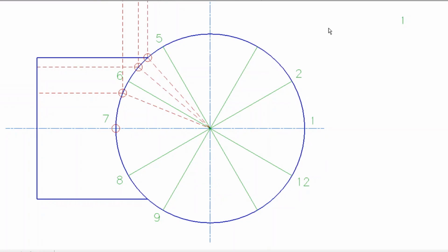With the grade 11 drawing, you're going to be using 4, 5, 6, and 7 directly as your points of penetration, but because this cylinder here is smaller than the main, your penetration points will not line up with 4, 5, 6, and 7. The only one that will line up is 7 itself. So 7 will act as a penetration point, but 5 and 6 will not.